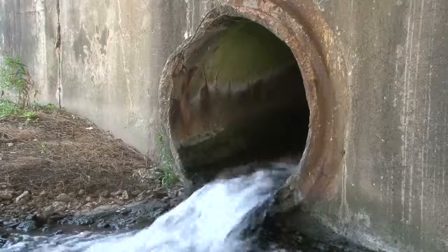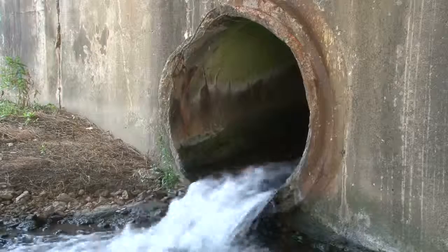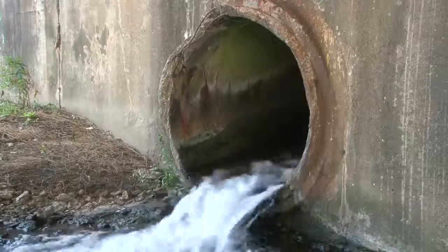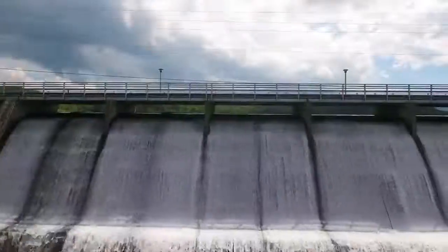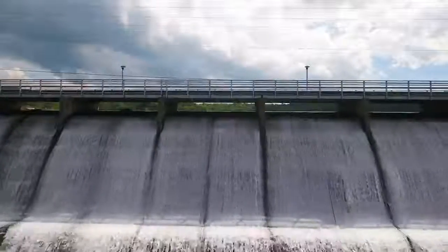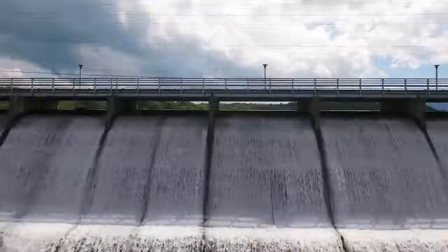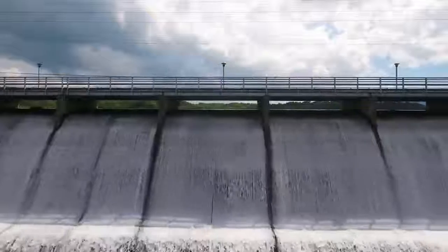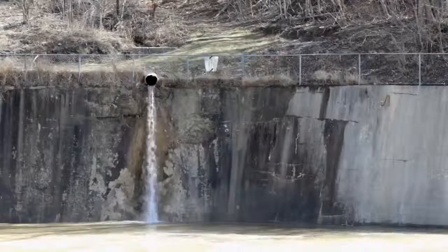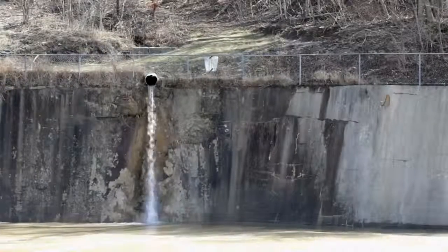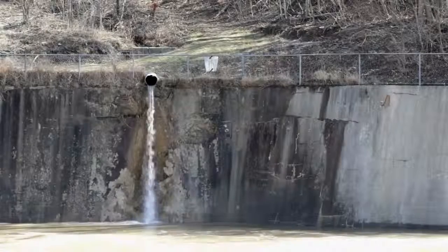For example, when we put water in a culvert rather than allowing it to flow over a roadway, it can pick up speed in the pipe. When we line a ditch or creek with concrete, the smoothness speeds up the flow compared to natural conditions. And when we make releases from a reservoir behind a dam into a spillway, the water can come roaring down at extremely high velocities. This supercritical flow can cause erosion and eventually lead to failure of the structure.